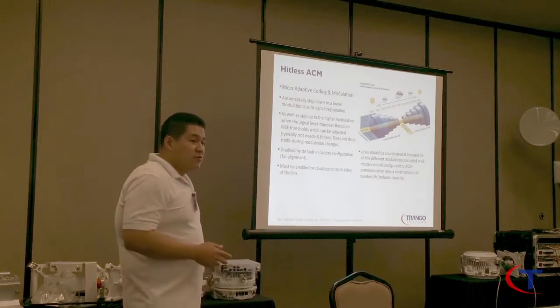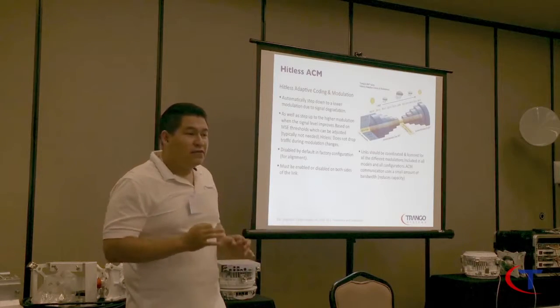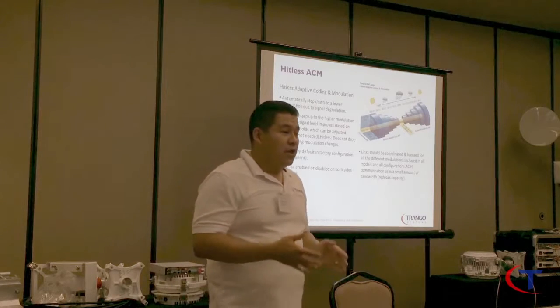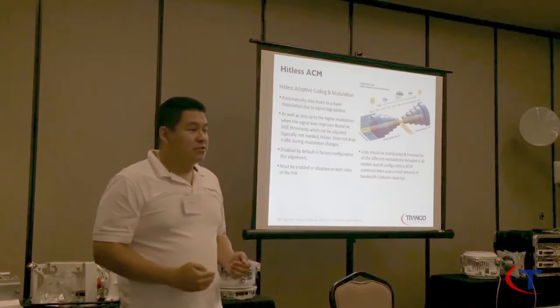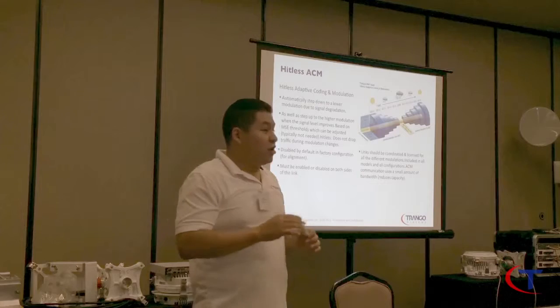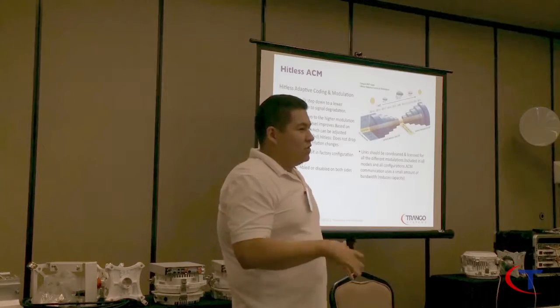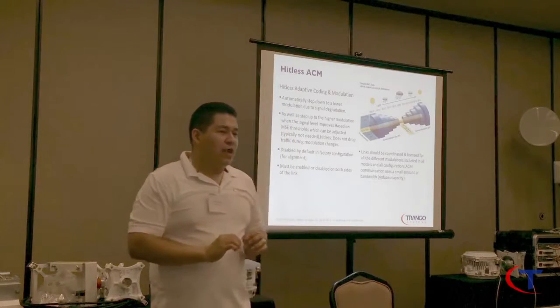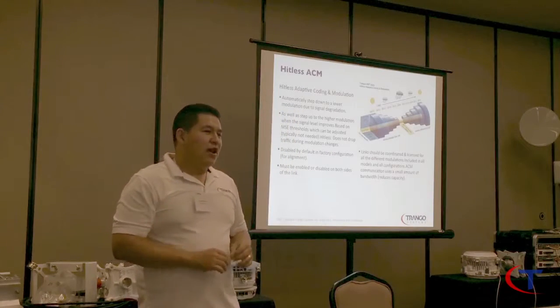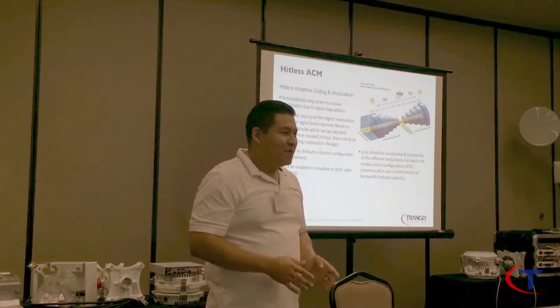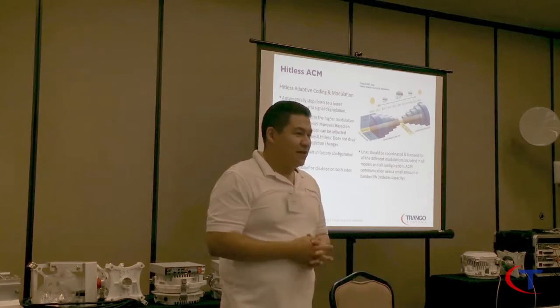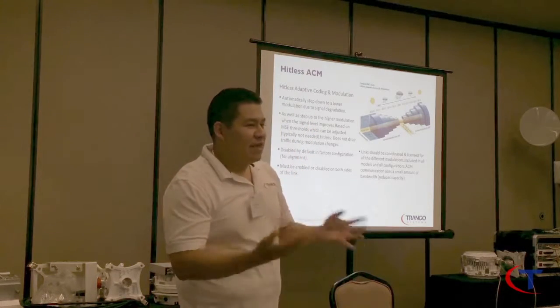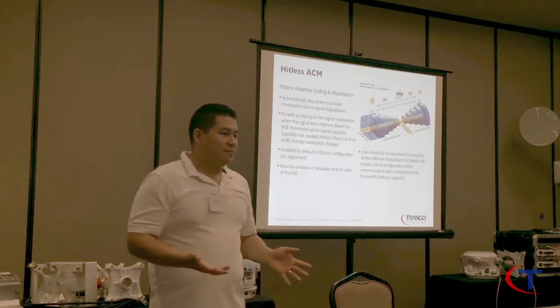In the Orion Lynx series, you cannot turn off ACM. ACM is on by default. In our previous radios, the Pluses, you could enable ACM on or off. Good things and bad things. In the previous series, if you did not enable ACM on both sides, you could have the greatest link in the world, but what happened? It did not lock at all. In this one, ACM is always on, so there's no problem with that.